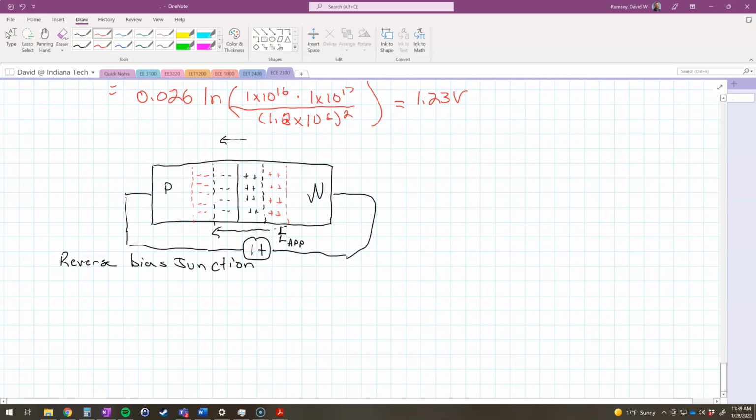And now remember, you might say, well, what happens if you increase the depletion region all the way to the end of the P and N side here? Well, first off, this isn't actually how the devices are physically built. This is just a graphical representation of the PN junction. But even if you were talking about putting it all the way out to the ends of the device, it doesn't matter, because remember we said that there's essentially no free electrons or holes in the depletion region.